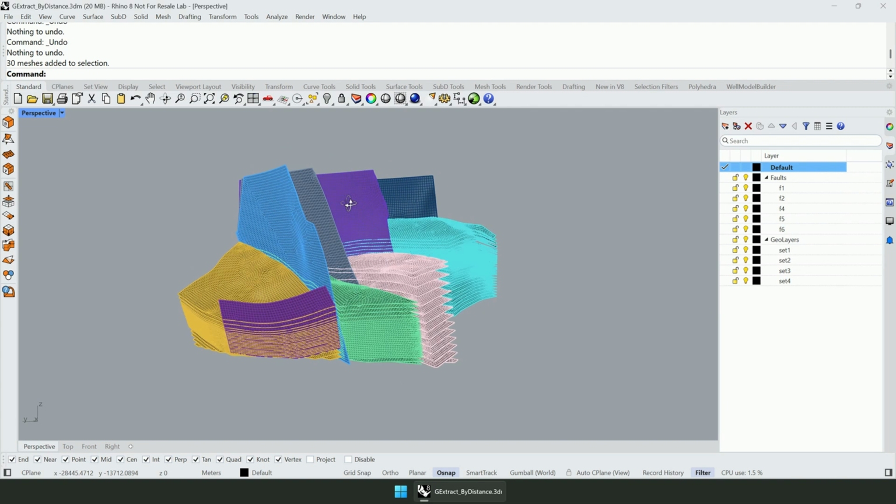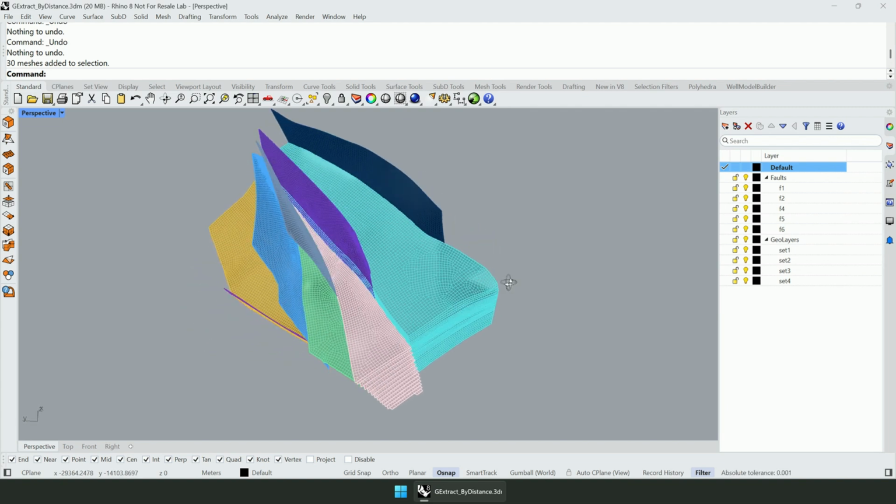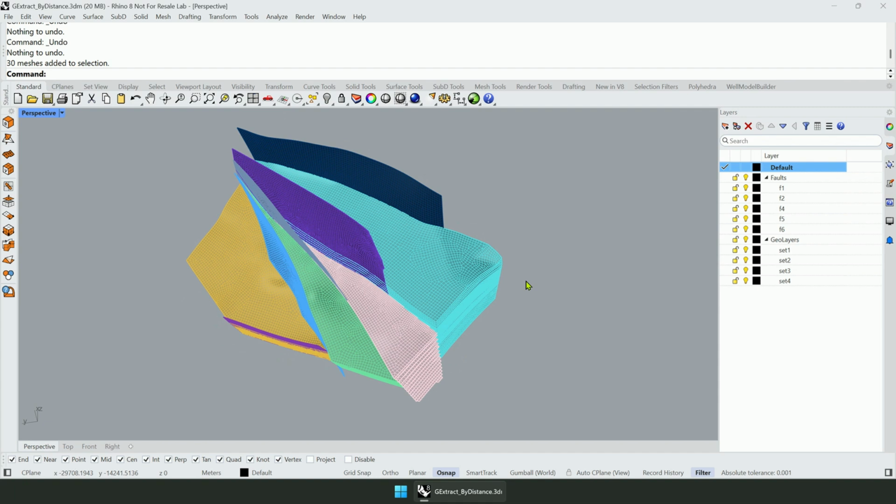And these vertical meshes represent some geological faults. Quite often engineers would like to separate interactions between different types of objects or different types of meshes in their model. This can be achieved by separating faces that are located nearby these objects. For example, we can just remove faces of geological layers located near the faults.